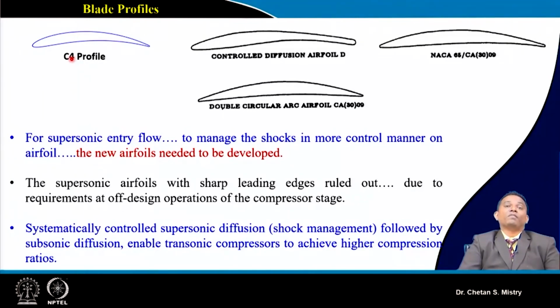So we will have flow separation at the leading edge, and we can say my entire blade or entire aerofoil will go under stall condition. So this sharp leading edge needs to be addressed. That is what demands having curvature for the leading edge and trailing edge.